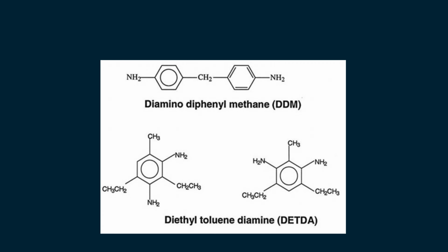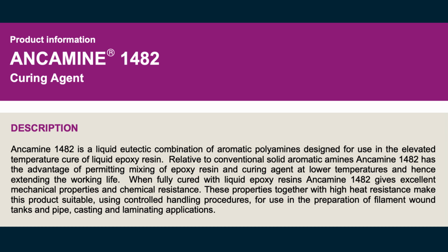Other aromatic amine systems. Aromatic amine eutectics. Eutectic mixtures composed of various aromatic amines are also available as epoxy curing agents. These materials behave similarly to MPDA or MDA in terms of curing chemistry but are liquids at room temperature with viscosities around 2000 cP. Because of their liquid state, they mix readily with liquid epoxy resins without requiring heating.